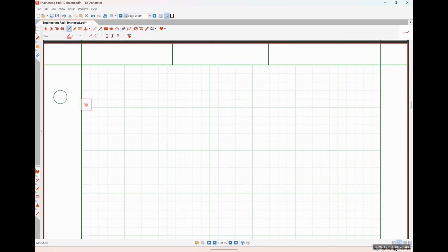So let me come down here. Let's write multiplying signals. So I'm going to take two logarithmic amplifiers. So let's call this V1 into some resistor R. I think I have to draw this smaller because it's going to wind up being 4 total op amps.